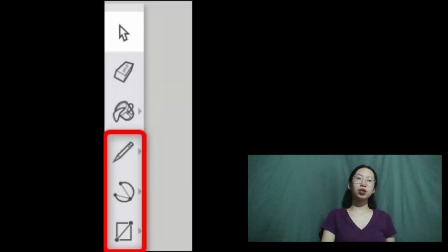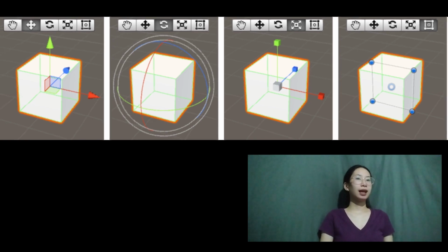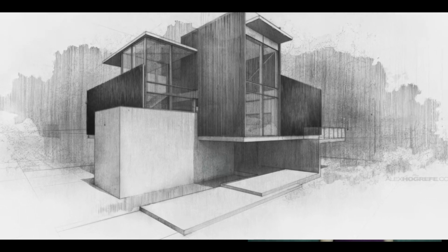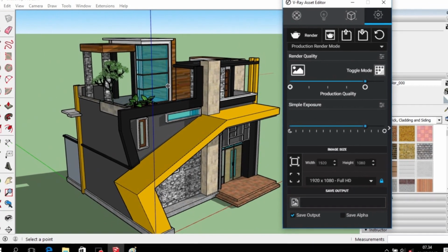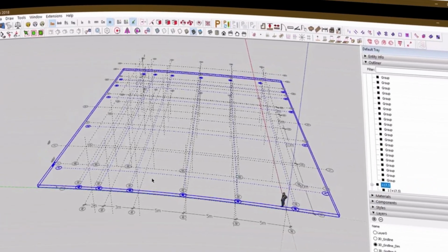You have a large range of tools as well to help you shape these simple forms, like extrude, change scale, rotate, move, shift, and others. In addition, you can change the style of the drawing in SketchUp, having multiple choices for that. You can use a black and white sketch, colored sketch, direct lines, etc. Besides the tools that SketchUp offers, you can benefit from the add-ons offered to help you model quickly and efficiently.